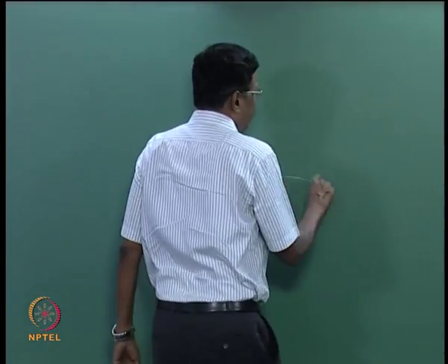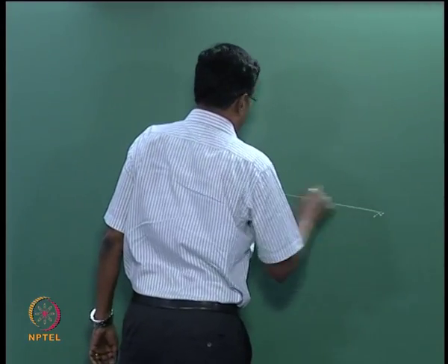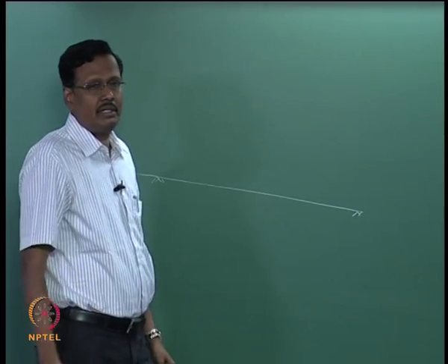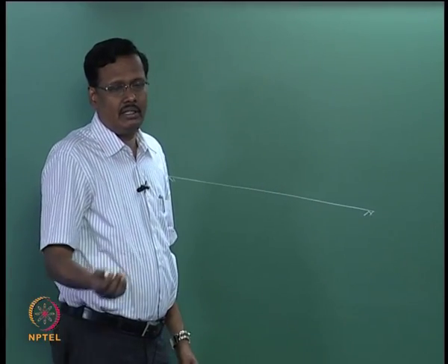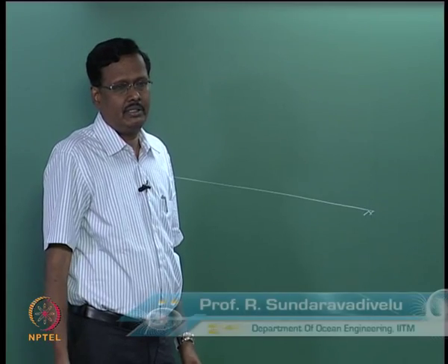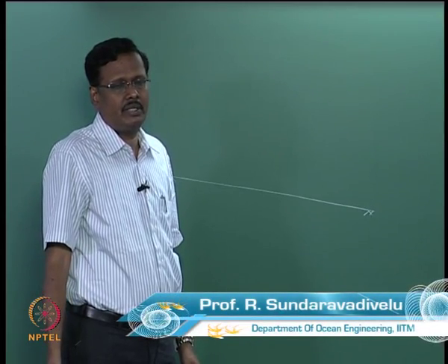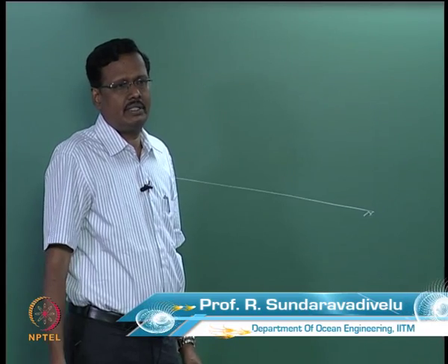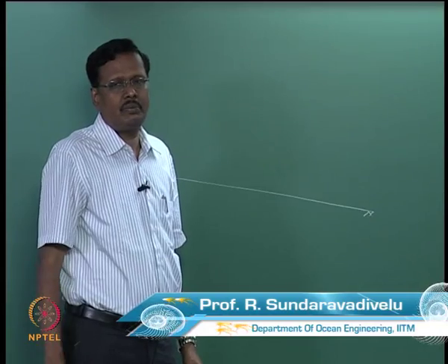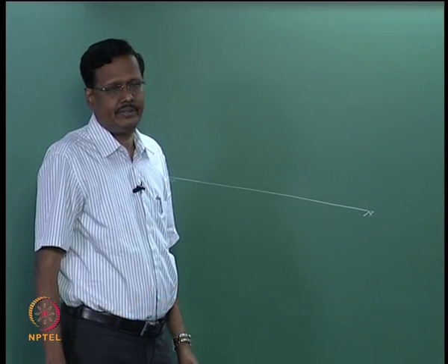Did we discuss breakwater design? Then we discussed Hudson's formula and other things. All these things are based on waves: how much wave absorption is required to resist the wave, what should be the weight of the stone. There is no soil property coming into the picture, right?